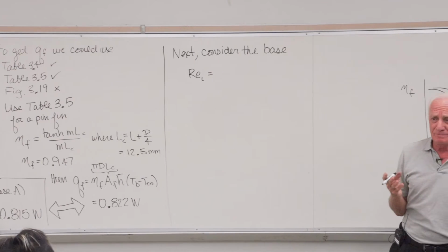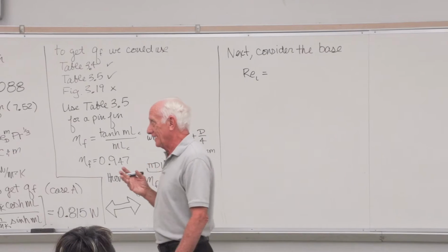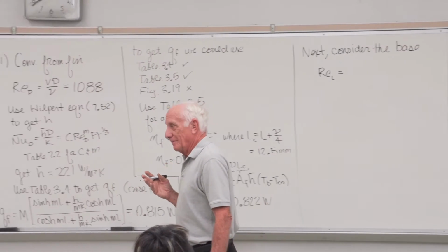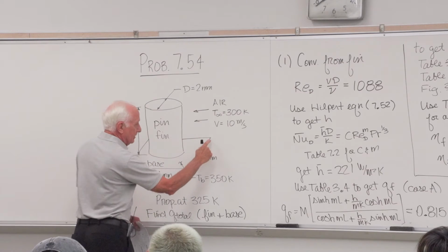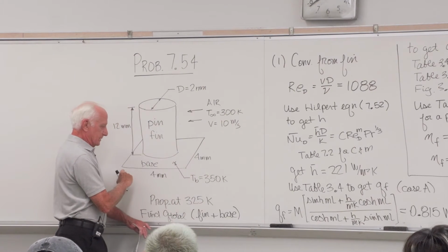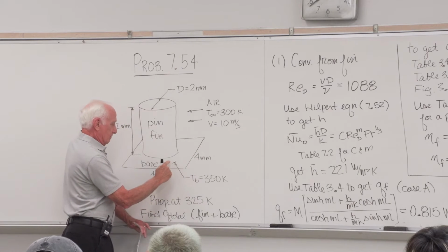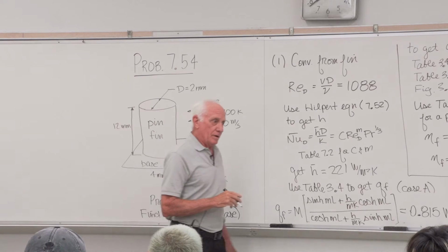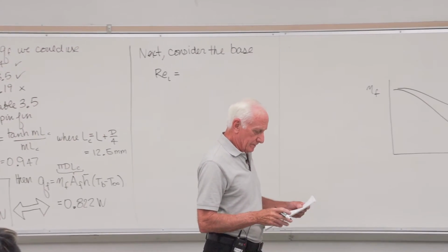We're going to consider it to be a flat plate. Chapter 7, first part, chapter 7, flow over a flat plate. Maybe there's a boundary layer buildup here at the front. Oh, this air's going this way. Here's the front, x equals 0. Here's x equal L. Maybe a boundary layer builds up, and the boundary layer might be laminar, might be mixed, might be all turbulent.